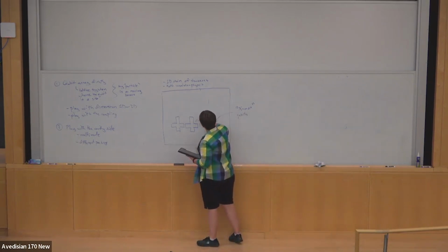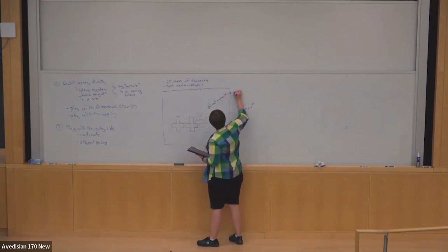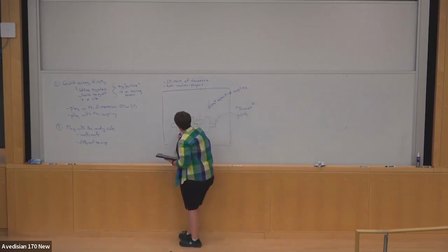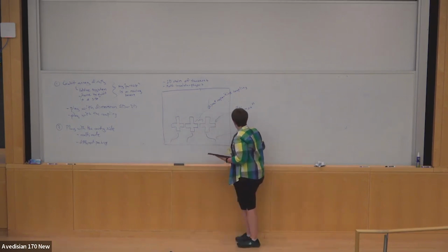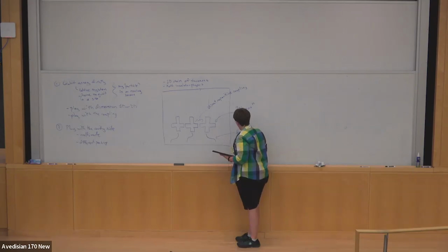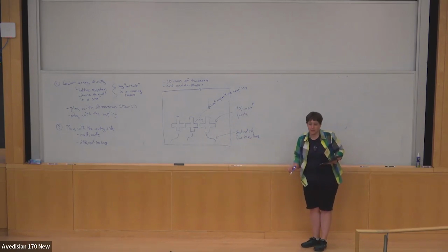They have a direct capacitive coupling. Each qubit has a dedicated flux bias line. These are used to apply a different magnetic field to every qubit.